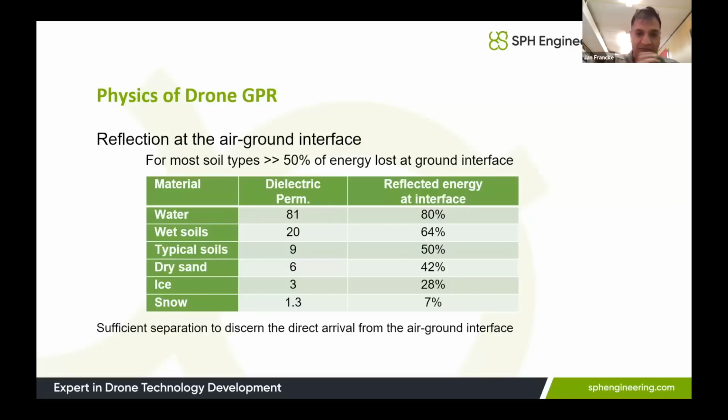So let's talk about the physics very, very simply. Radar works off the reflection between different dielectric permittivities. What does that mean? What is this word dielectric? It actually, sorry, Jonathan, has absolutely nothing to do with conductivity. When it comes down to it, it's really about moisture content. So we're going from one moisture content to another, and that could be very detailed when it comes to geology. Different rock types, different soil types in the matrix can have different moisture contents.